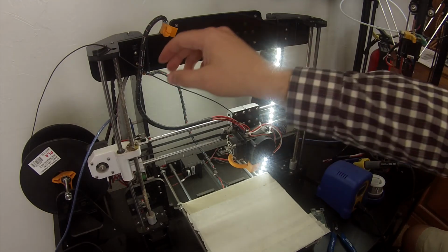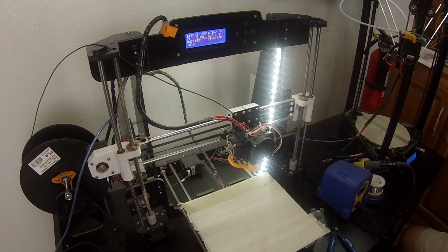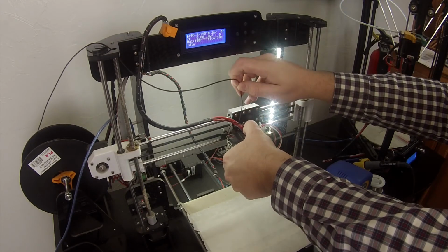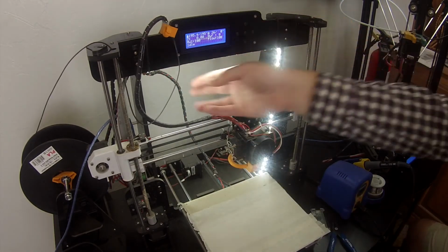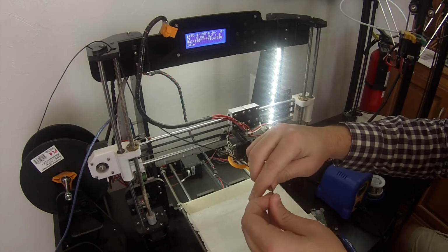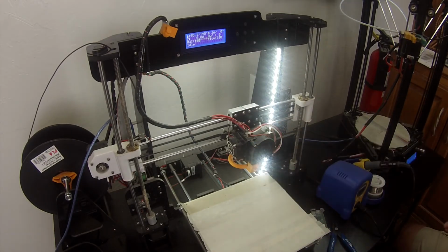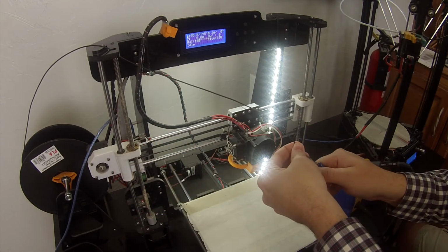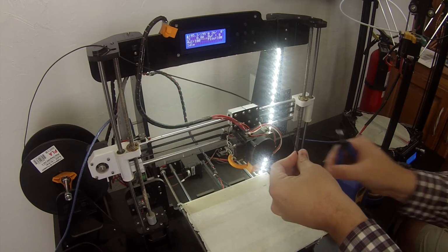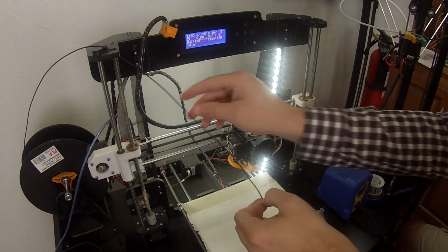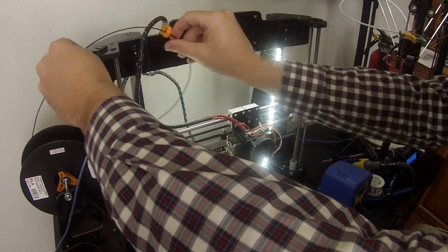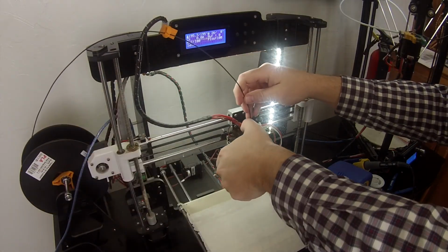So you can just take out the previous filament, and now I also realize that I've threaded this through a really dumb part of my printer, and I have to fix it anyway again. Whoops. So anyway, press that threaded relief, and you can see actually it's put a point on this because that's where it's fed into the nozzle. I made a very pointed filament end. So I'm going to go ahead and put another slanted cut on the filament to make it easier to feed. I'm going to unthread this from that hole in the printer. I don't want to feed it through there. I was just holding it there earlier and mistakenly left it.